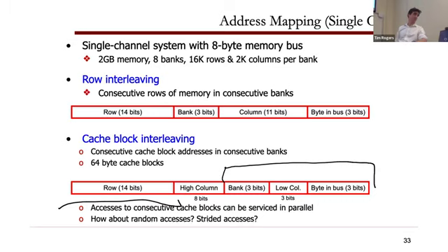Okay. Other questions? Yep. What is more expensive energy or latency wise, striding across a column or striding across a bank? So energy wise, cross bank is worse, right? Because I have to light up N banks. So you're paying the cost of all those sense amps being on, when you're going to turn on the whole row no matter what you do, right?